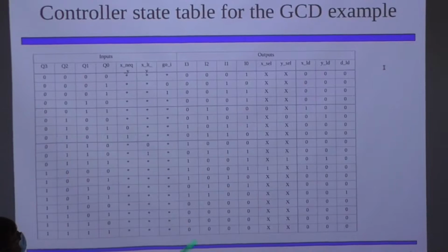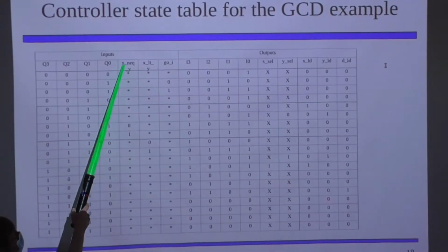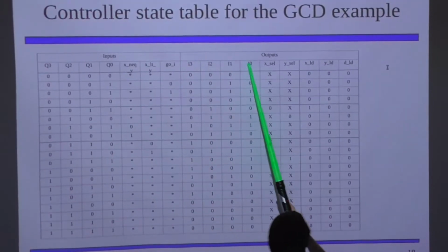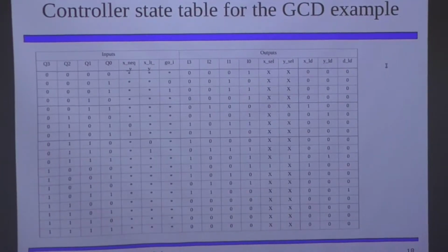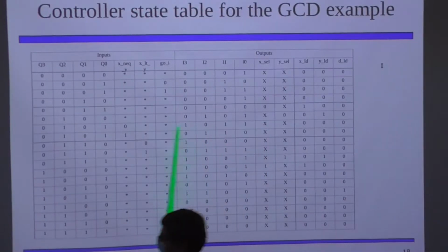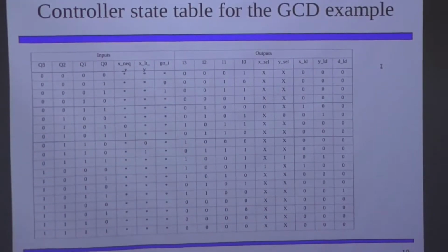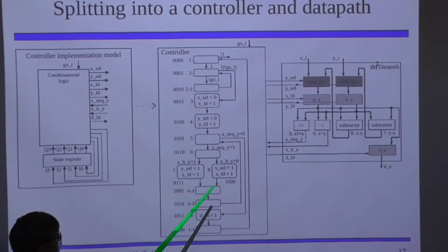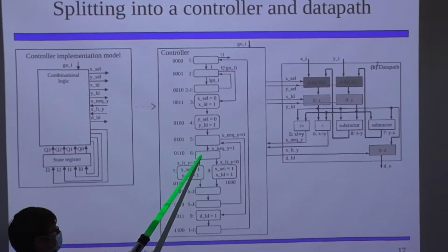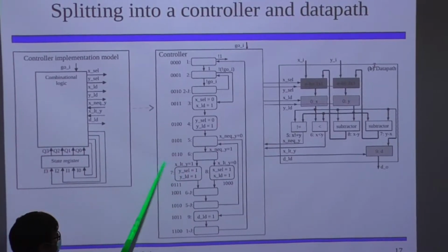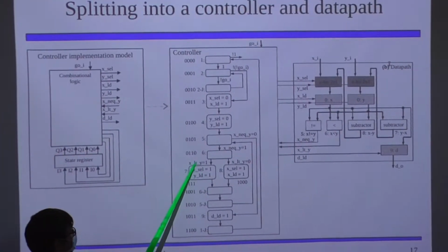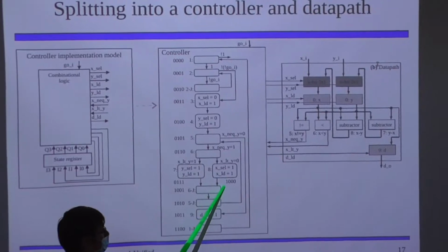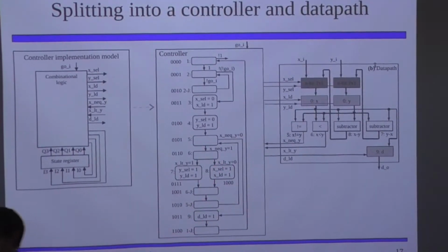That's good so far as it goes. We also have the inputs coming in, right? Obviously, the next state bits are also of some interest here. Let's take, for example, one of those states where we're actually making a jump. So let's consider this one. We go to state 0, 1, 1, 1 if x, L, T, y, x is less than y, is 1. And we go to 1, 0, 0, 0 in the other case.